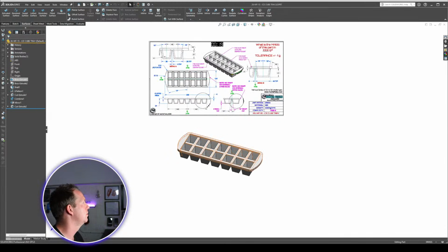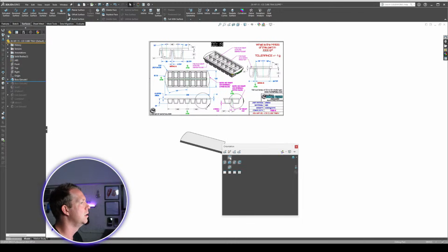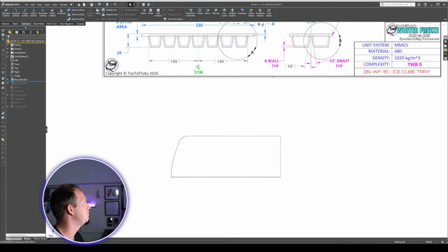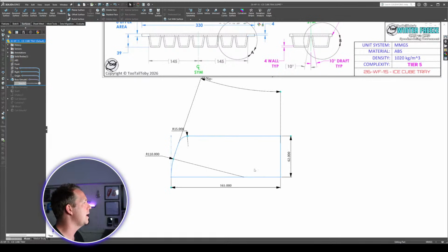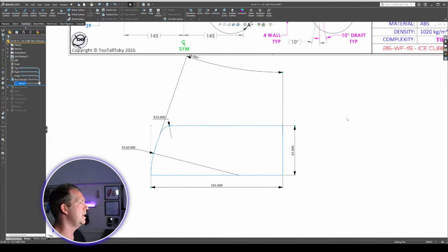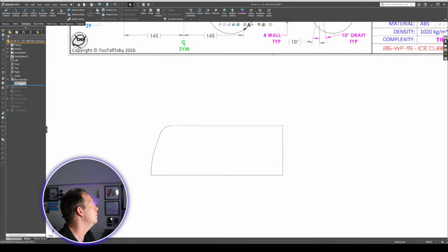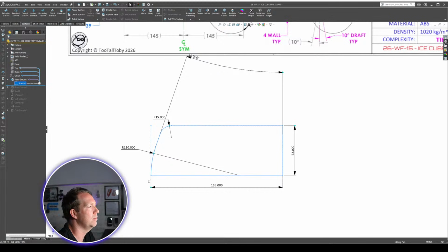So first off, I was a little bit surprised that neither guy went for just doing a quarter of the extrude to start. And if they had done this, it would have made it a lot easier to edit the sketch and put this straight line in afterwards. Reason being, you only have to do it in one place instead of in 4 places.